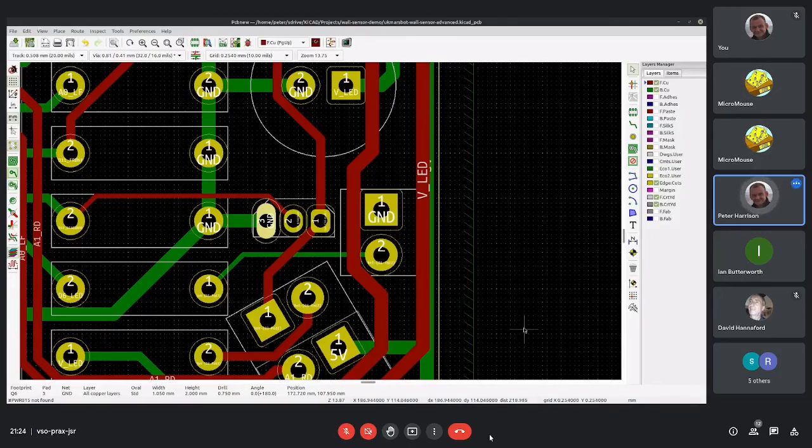Yes. Honestly, if you think you're going to be using a particular house, it would be prudent to check the design rules before you start. And of note in that sense is, I think PCBWay and probably JLC PCB allow clearances down to something like 3 or 4 mils, right, which is absurdly tiny.